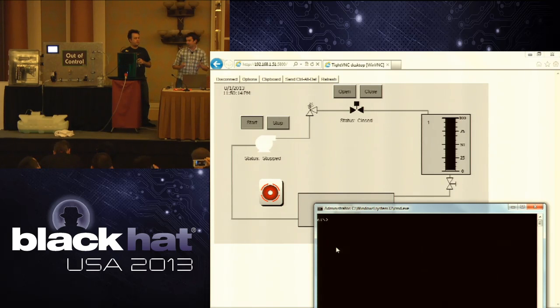This just shows how easy it can be to force the outputs of a process. And this is not binary exploitation. This is just telling the PLC what points to turn on and off and what its worldview of the process is, and telling it to disable its own logic scanning. All it does is what it's told to do. And the operator always makes control decisions based on what the PLC is giving it.